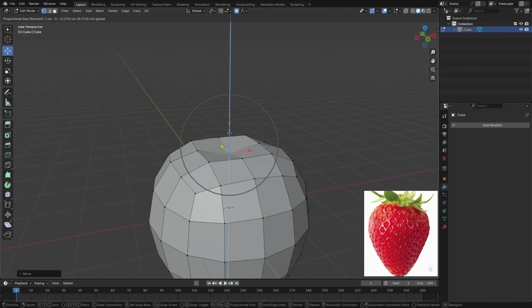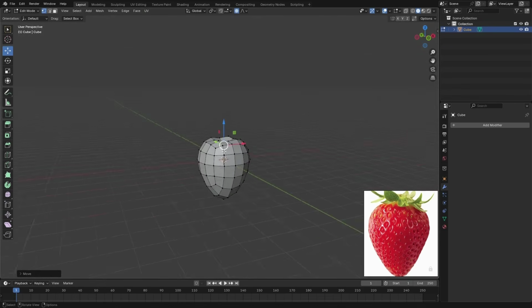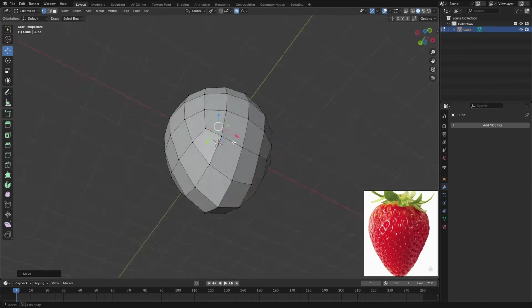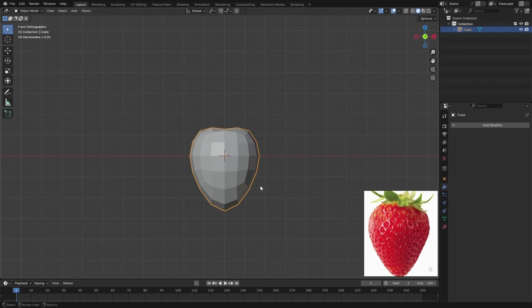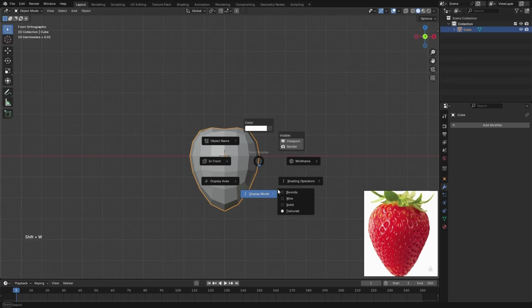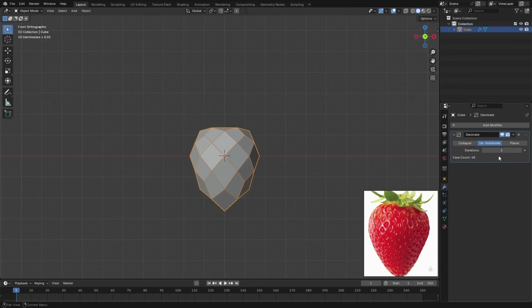Maybe even more. With the sculpt brush, we're gonna get this edge kinda pop out. So that's our basic shape. Back to object mode. All right, let's first of all enable the wireframe right there. Let's go ahead, add decimation modifier and unsubdivide 1 level.